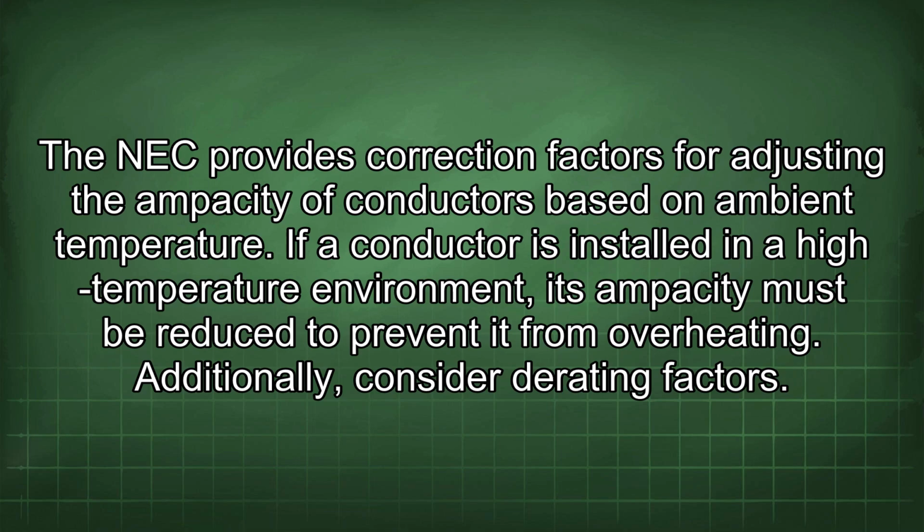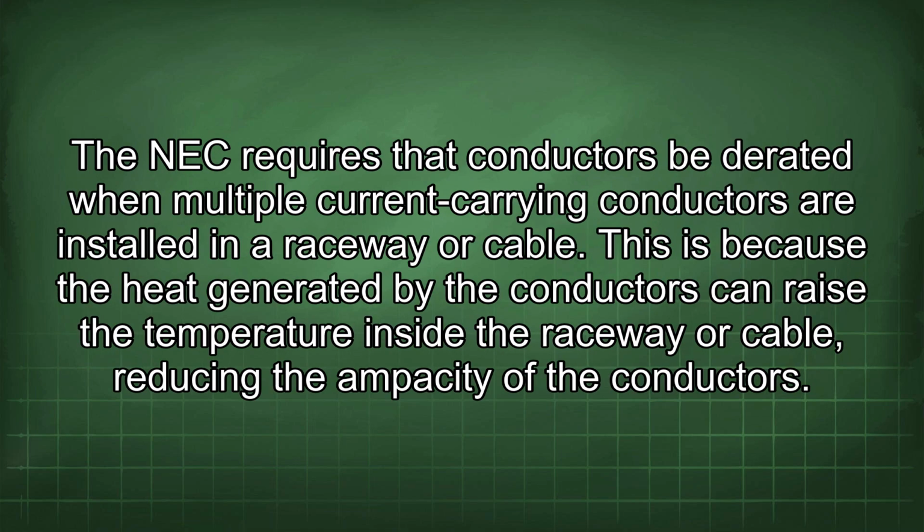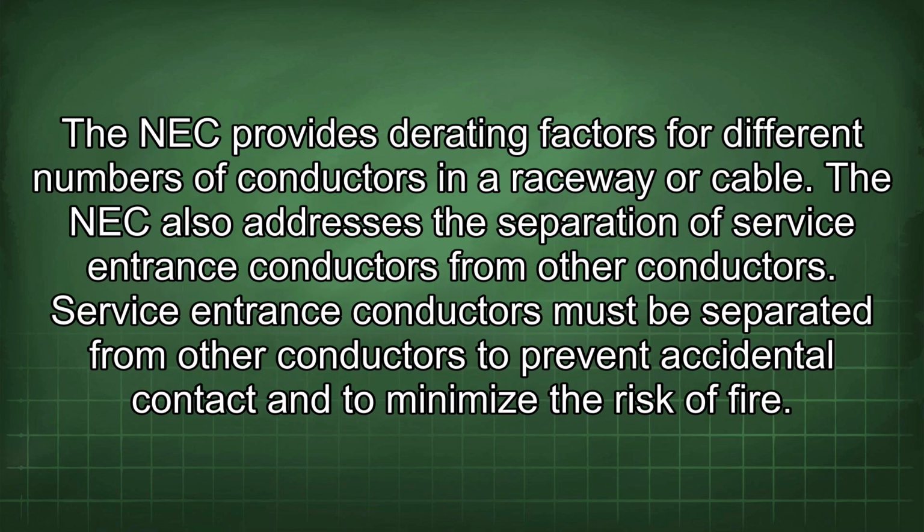Additionally, consider derating factors. The NEC requires that conductors be derated when multiple current-carrying conductors are installed in a raceway or cable. This is because the heat generated by the conductors can raise the temperature inside the raceway or cable, reducing the ampacity of the conductors. The NEC provides derating factors for different numbers of conductors in a raceway or cable.